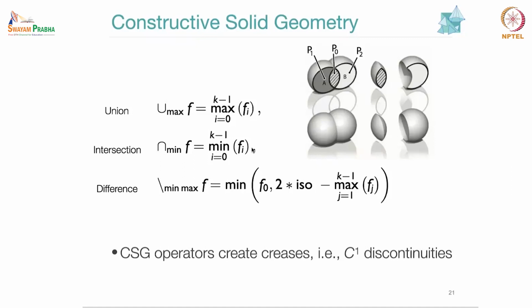Yeah, exactly. To define a complicated shape, you define simple shapes with these implicit functions, and then use constructive solid geometry, such as union, to define very complicated shapes. And in generating the basic shapes, we are generating them by the distance function, right? Yes, basic shapes are almost always generated using distance functions.